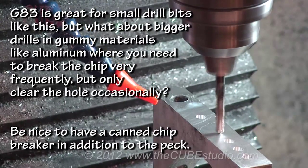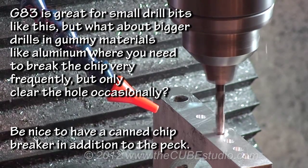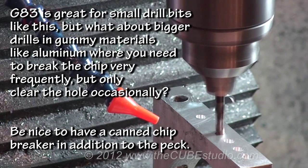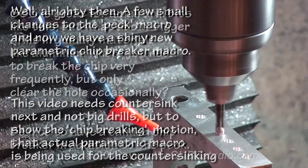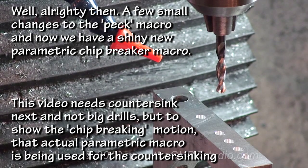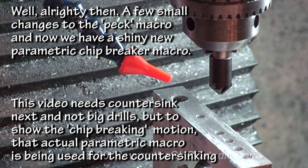G83 is great for small drill bits like this, but what about bigger drills in gummy materials like aluminum, where you need to break the chip very frequently but only clear the hole occasionally? Be nice to have a canned chip breaker in addition to the peck. Well, alrighty then. A few small changes to the peck macro, and now we have a shiny new parametric chip breaker macro. This video needs countersink next and not big drills, but to show the chip breaking motion, that actual parametric macro is being used for the countersinking.